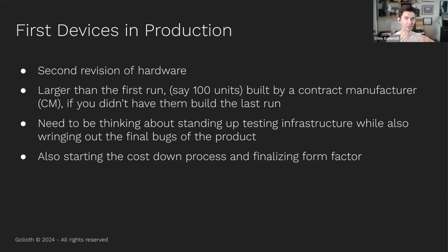You want to be thinking about things like test points on your boards and how that might be interfering with things. If you're really size constrained, you need to make sure that you have enough room for test points, you have enough capabilities in there. Maybe you have additional chipsets that give you more visibility into the final product, and in a contrary kind of motion, you're not giving so much access that it's very easy to extract your firmware later, and someone's not able to take over your product without you wanting them to.